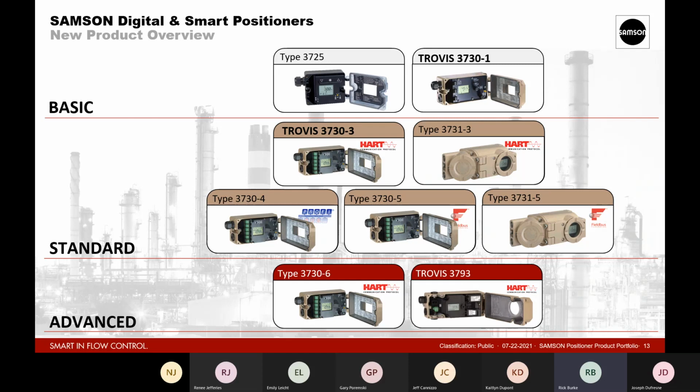One example of where we used a whole bunch of these because of their versatility and the options that they have is back in 2011, there was a chemical plant. We supplied over 50 on-off and linear control valves with these positioners for a SIL 2 upgrade. So this whole area was being reclassified as SIL 2 and hooked up to an SIS safety instrumented system control system.